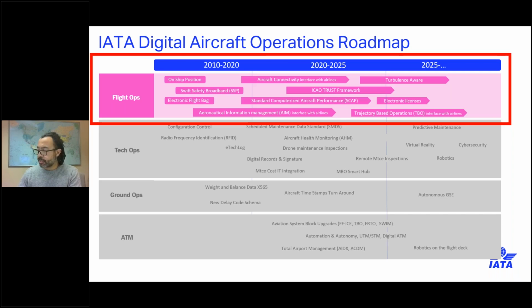In terms of this conversation, one should take into consideration the work being done at the EFB subcommittee, which is to develop standards applicable to EFB and thereby, by extension, connectivity. Peter and his team have been instrumental in working with the FAA on AC-120-76, which I gather is to come out soon, and the EASA AMC 2025. Just to let you know, the ARINC standards comprise hardware and software specifications as they apply to interfaces, application control, wiring and connectors, and data protocols.